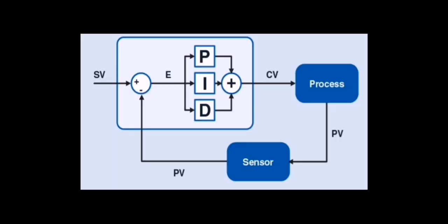The system operates according to an automatic control principle. It measures the ambient temperature using a sensor, compares it to the set point set by the user, and then acts automatically. If the temperature is below the set point, the system activates the heating. If the temperature exceeds the set point, the system activates the ventilation.